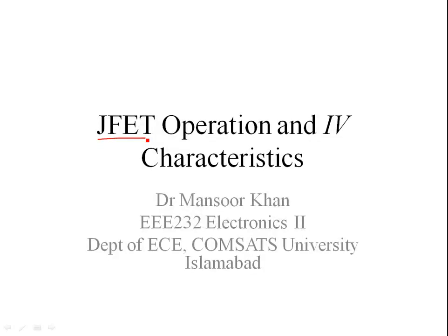About junction field effect transistors, their construction, operation, and their IV, or current-voltage, characteristics. So previously we have talked about MOSFETs. It turns out that we have other field effect transistors. So we have junction field effect transistors. We have MESFETs, metal semiconductor field effect transistors, which are constructed employing a Schottky barrier instead of an insulated gate.